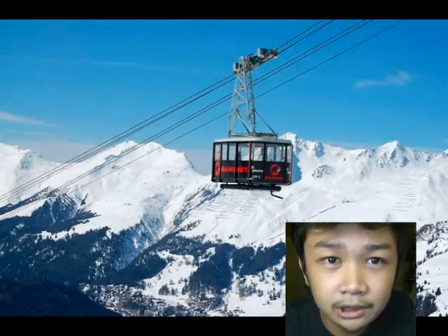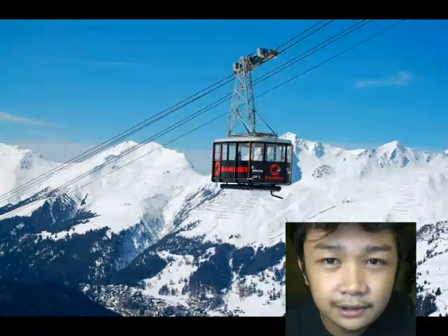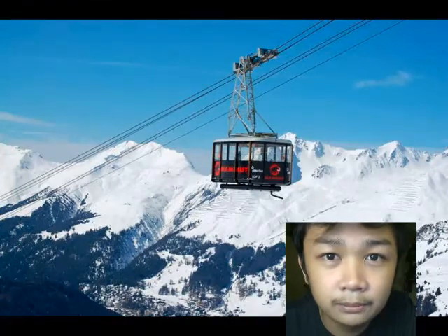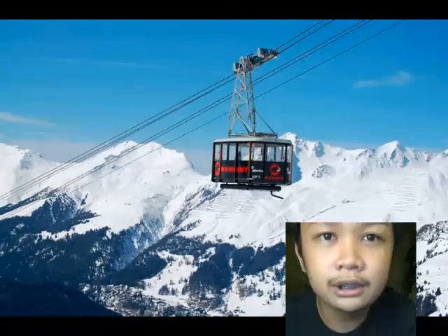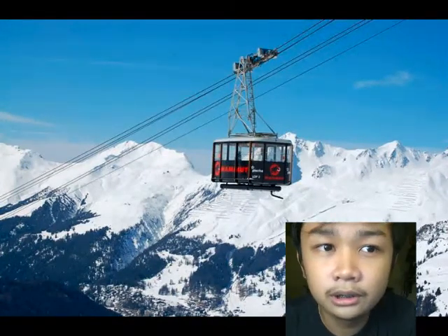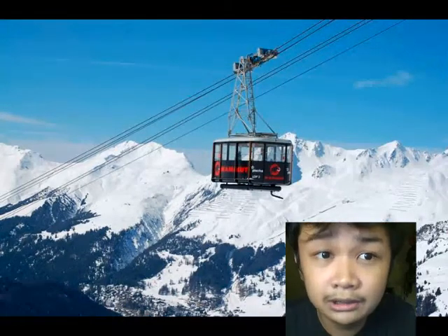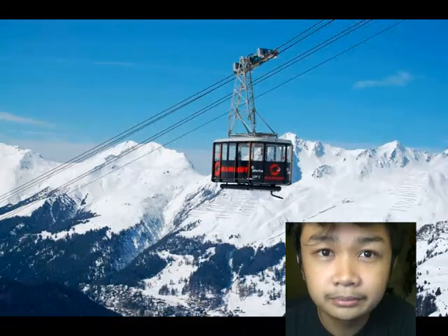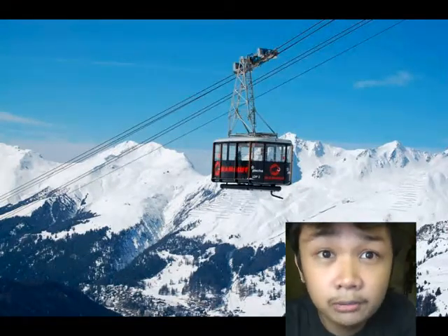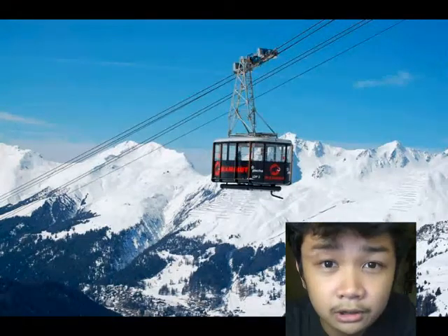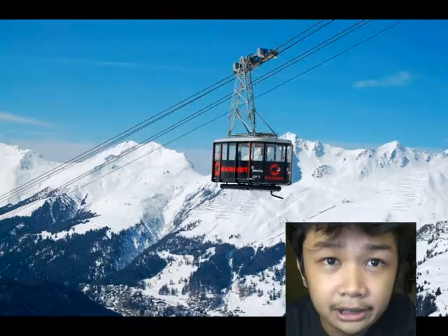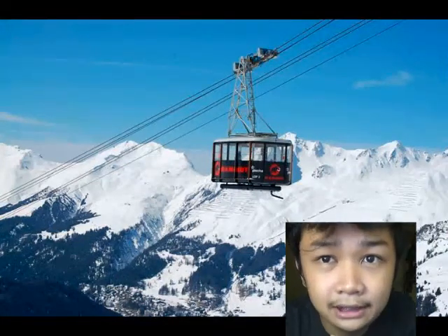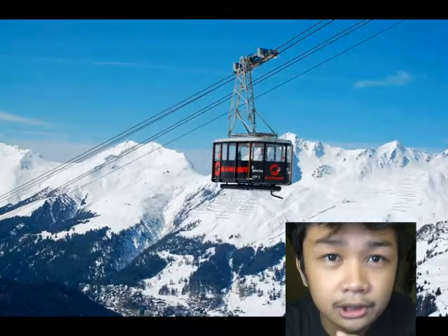The cables are over an inch in diameter, with 6 steel strands of 19 wires each wrapped around a core of sisal. Each cable has a mechanical grip that latches onto the cable, much like a huge pair of pliers. The gripman can take or drop the rope as needed to start or stop the car.